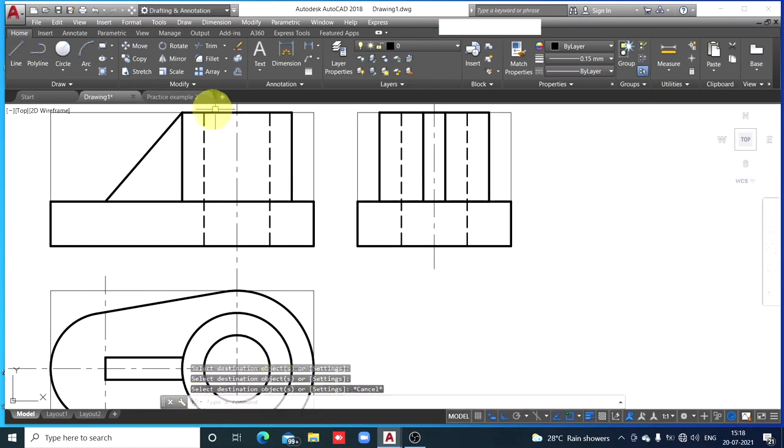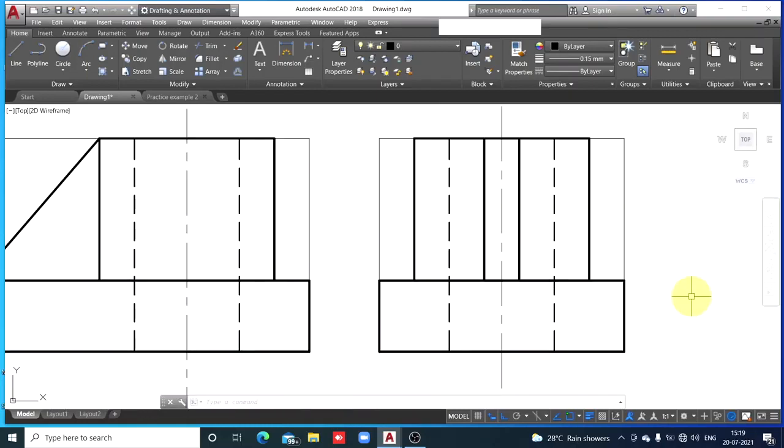Okay, now if I ask you where is this cylinder in the side view, so show me this rectangle. And where is this triangular plate in the side view, so show me this rectangular strip. Side view of the cylinder, that is this rectangle, and side view of this triangular plate, that is this rectangular strip. Side views of these two parts overlap. So when this happens, you check for hidden details.